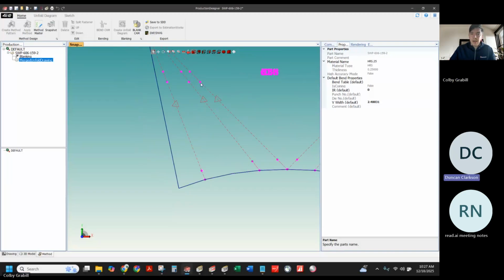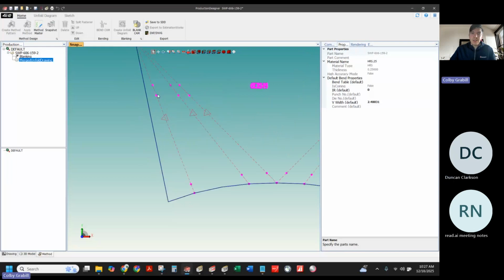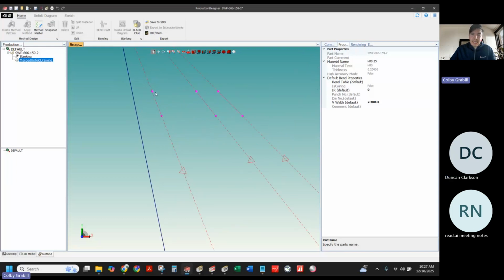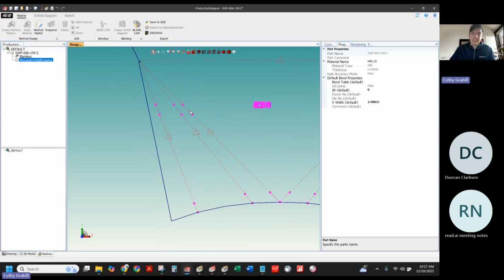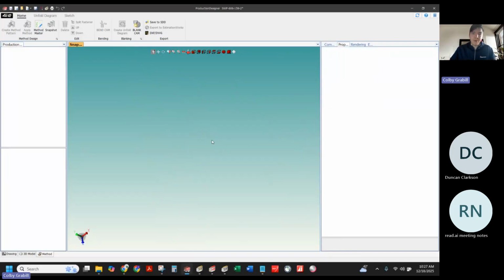I believe it's a mark so that the guy doing the press brake can connect those two lines and has a visual indicator where to align those bends. Okay. So this exact length and exact placement has some tolerance to it, it's not exact.